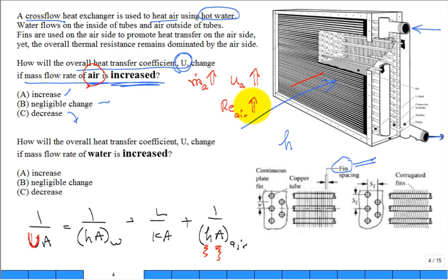All right. Hey, you know what? From the perspective of the air, I know you could think about it flowing through passages, which are on the sides by the fins and then the tubes on the top and bottom, or you could think about it as just flowing over one surface at a time, external flow or internal flow. Internal flow through a channel or external flow over the fins, right? But our general relationship coming out of convection is that the Nusselt number is equal to a constant, Reynolds number to a power, Prandtl number to a power, about a third. Let's call that quits right there.